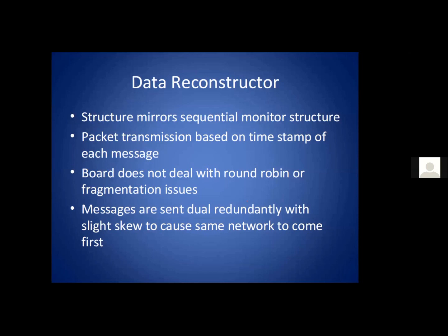So we know the exact data that went over the bus, the exact order that it went over the bus, and the timing. Now you feed that into our data reconstructor mode of transmission, and we will transmit out exactly what was received the last time. We'll do it for either everything, or you can say, do it for all the messages other than these particular VLs. And if you do that, then you can now attach the box that had the problem to our card.